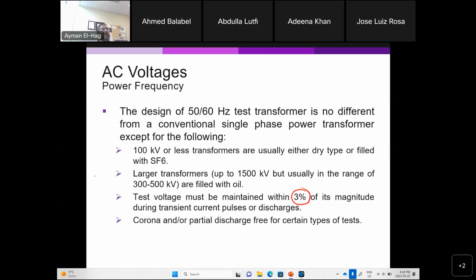Now, some of those transformers are meant to stress the asset at high voltage so as to measure partial discharge. There are different types of tests that can be conducted to generate stress on the insulation and see how much PD level it can produce. When you use this transformer for that specific application, you want to make sure that the transformer is PD free.